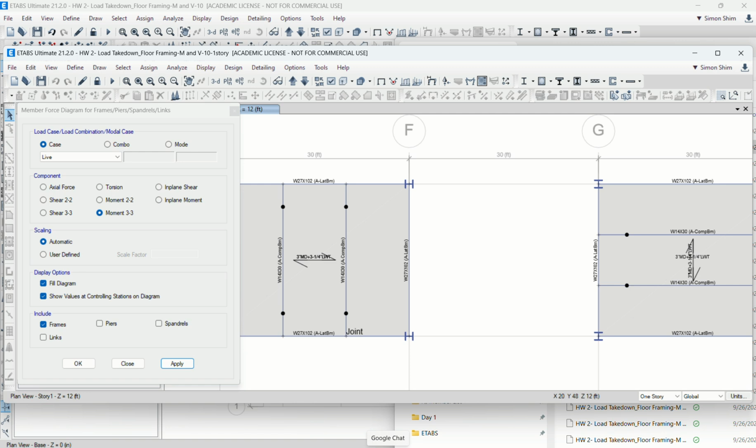If you rotate 90 degrees, you're going to end up with a totally wrong answer, because the metal deck should span perpendicularly and sit on the beam. In ETABS, this metal deck slab can then transfer the load properly. If you rotate 90 degrees, you probably get the wrong answer because the load is dumped from here to here, right? Which is not reality. You may get some number, but it's totally useless.